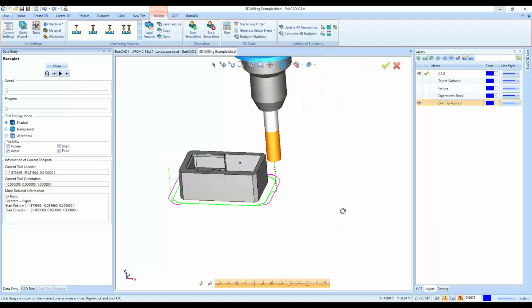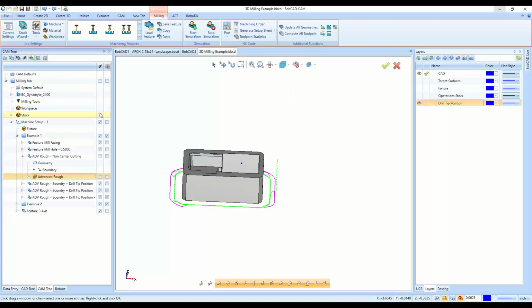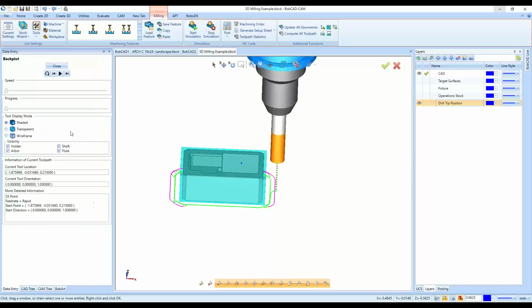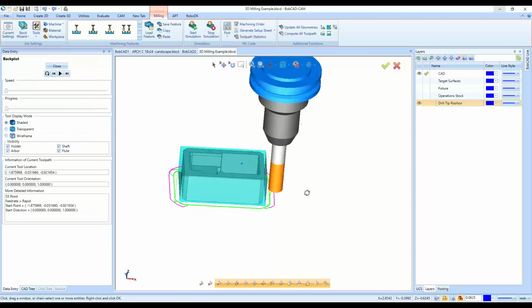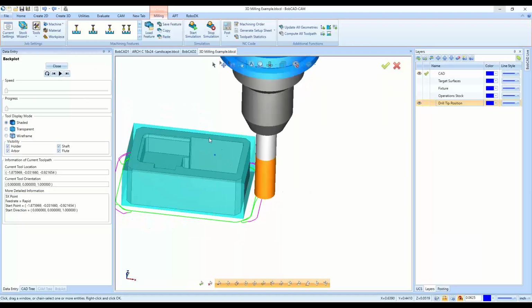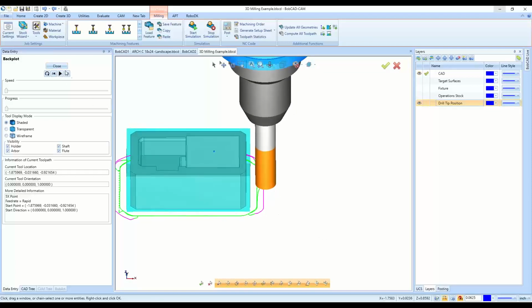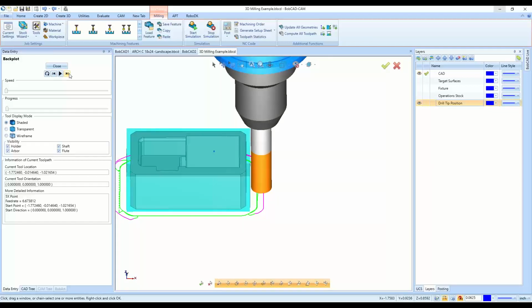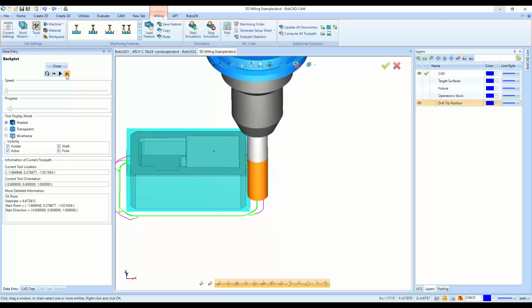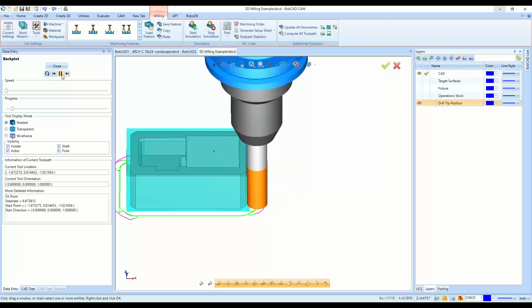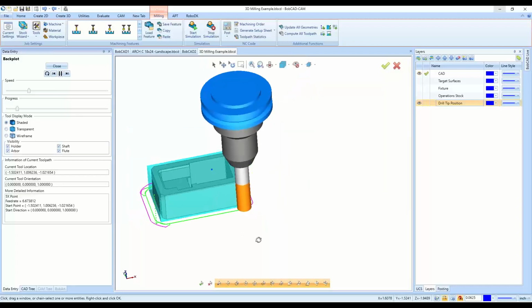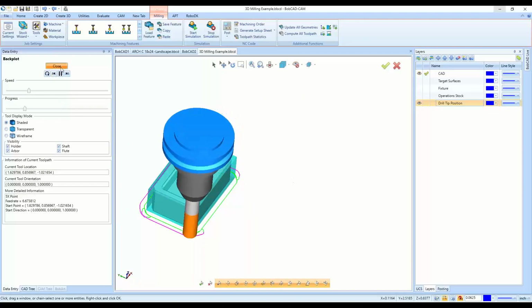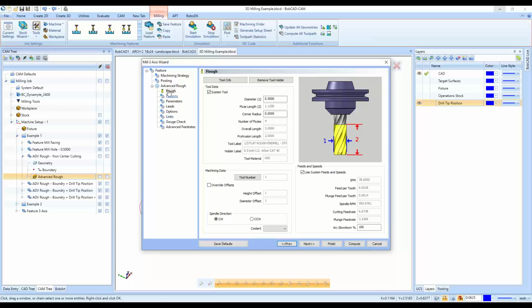And we can see, based on the stock, if I show that, the cutter isn't doing any of those options that I said of plunge, ramp, or spiral into the stock. It's actually starting from the outside and using the non-center cutting part of the tool to cut into the stock here. So that entry option is also in there. It is that checkbox in the advanced rough.